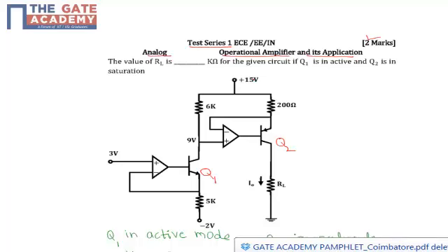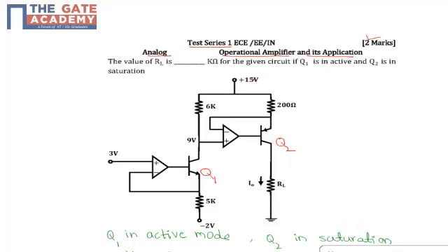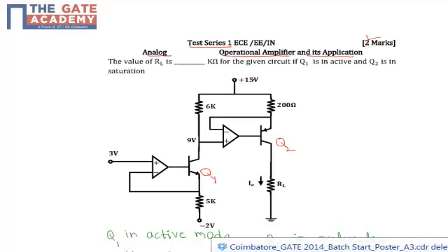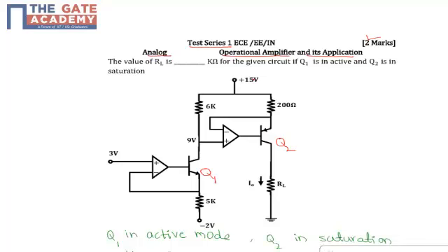First we learn what saturation is. When a transistor is in fully off state like an open switch, it is said to be cut off. Conversely, when it is fully conductive between emitter and collector, passing as much current through the collector as the collector power supply and load will allow, it is said to be saturated.